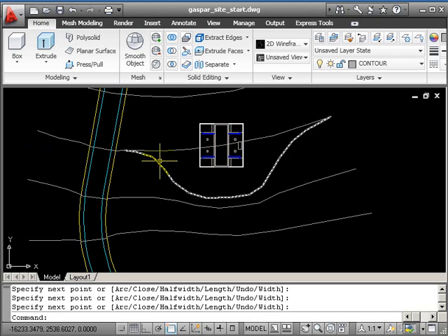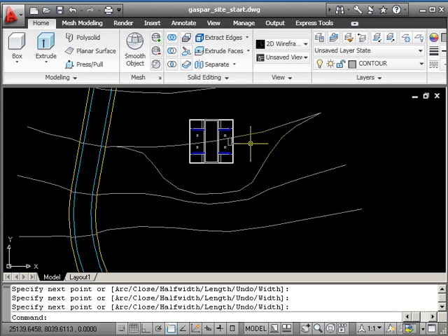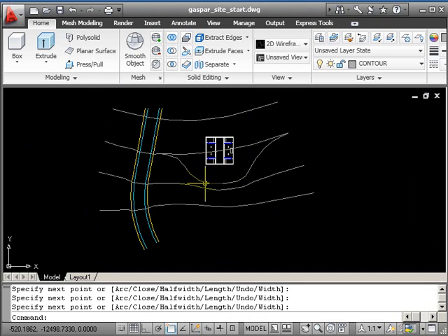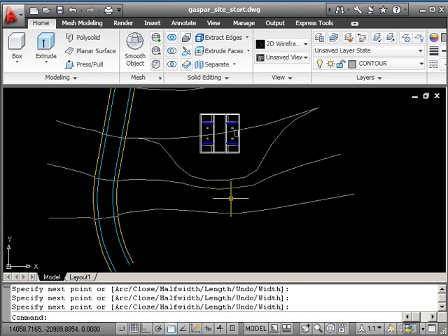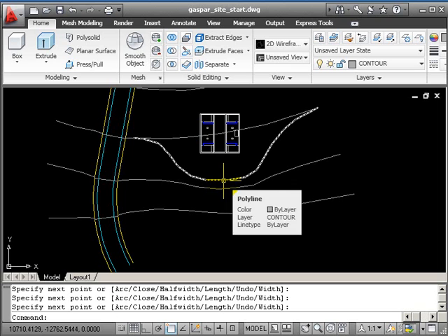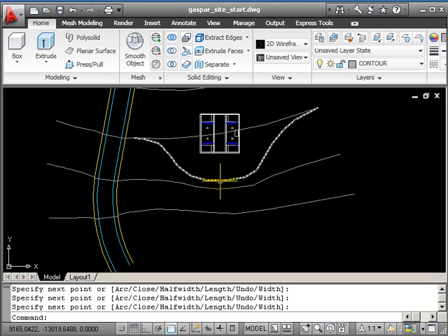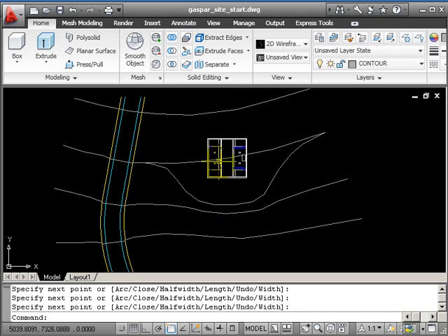Okay, it's a tiny bit of work, but it's very useful. So I've got an area, a bit of contour here that's kind of an existing one, and this is the proposed. So the impact on the site is fairly dramatic. We've got quite a steep bit of ground here. We're changing 4 meters in that small amount of space. So it's 2 meters between those two, but 4 meters between these two. So this is quite steep. So if you stood here, the ground would drop away from you quite quickly.